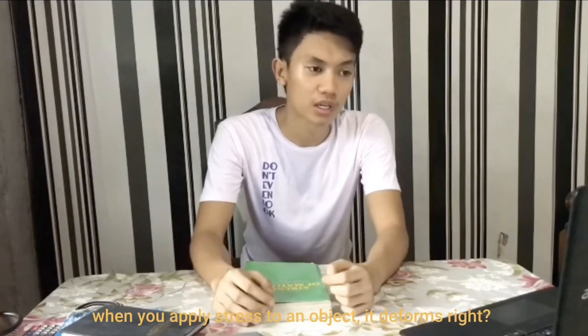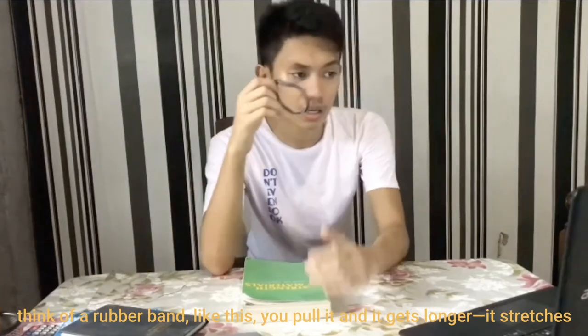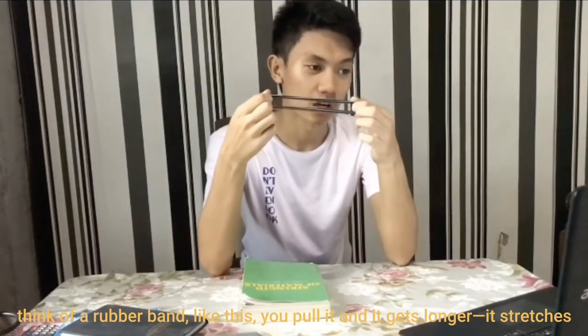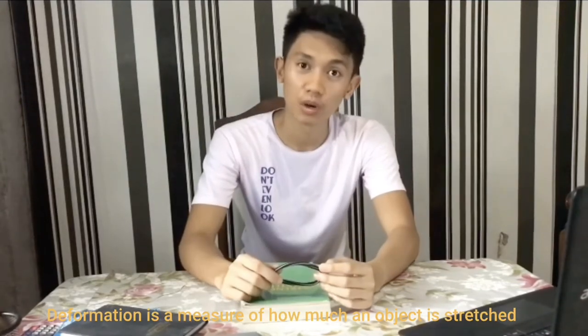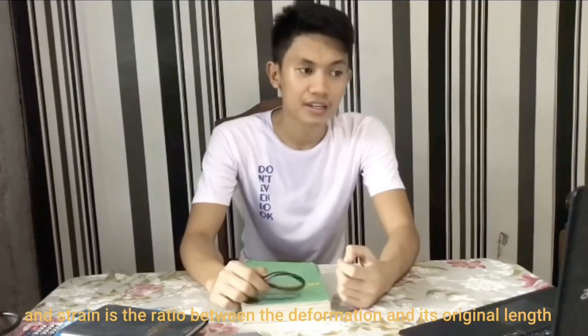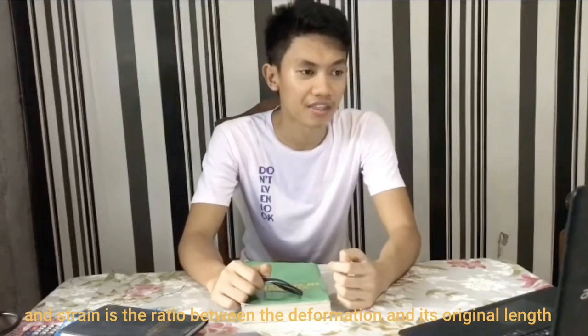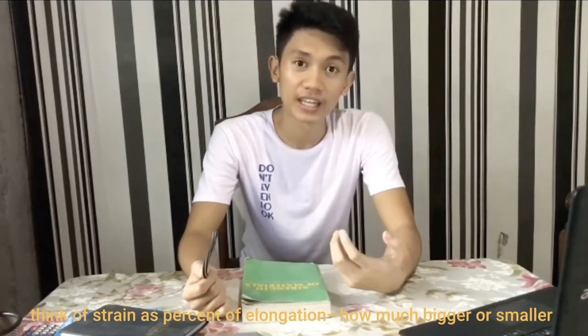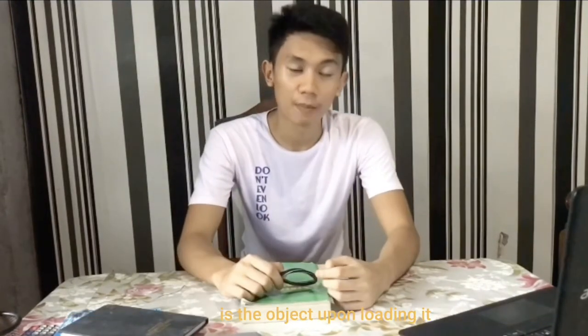For today, we will be discussing strain. When you apply stress to an object, it deforms, right? Think of a rubber band, like this. You pull it and it gets longer. It stretches. Deformation is a measure of how much an object is stretched, and strain is the ratio between the deformation and its original length. Think of strain as a percent elongation. How much bigger or smaller is the object upon loading it?